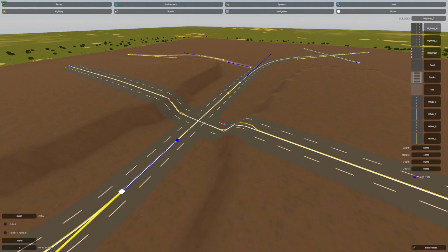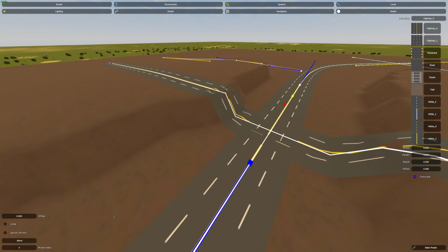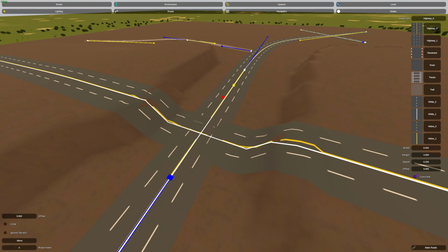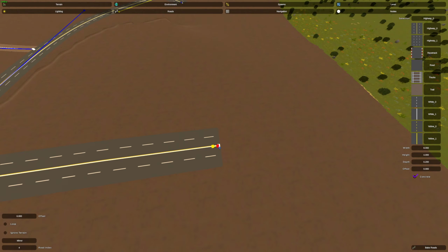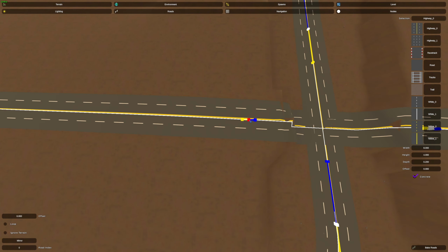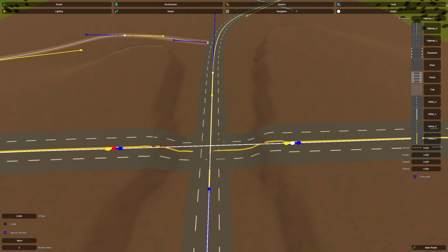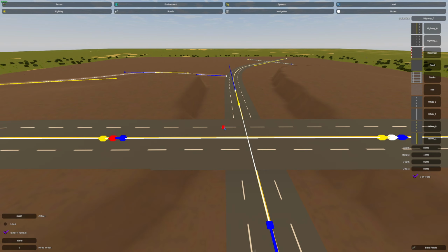Next, we will be talking about how to create floating roads. As you can see, I have an elevated area that I would like this road to pass over. The road has by default generated in this weird, unwanted way. I can add 2 points here and here, and select the Ignore Terrain option. As you can see, the roads are now floating over this intersection.